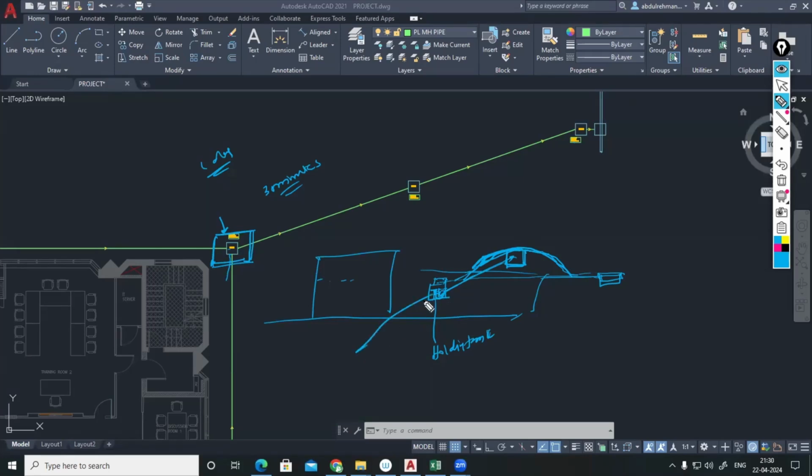The pump that we use to transfer the water from manhole number 5 to this tank is called a sewage lifting pump or sump pump. A sump is like a tank only. In the tank we connect a submersible pump, which we also call a macerator pump.